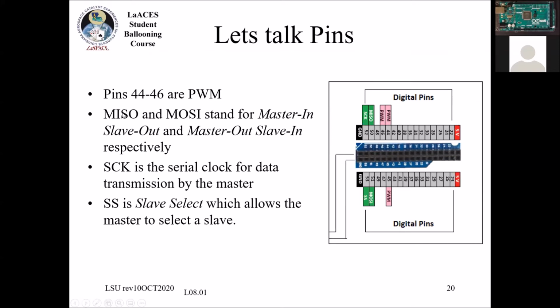So there's an input pin for the master that the slaves listen to, and the reverse. And again, you have a clock pin for synchronizing those signals. And then there's what's called a chip select pin. So if you have multiple slave devices, the way that you switch between them is you'll have a different select pin for each of them, and they will only listen while the appropriate select pin is high.